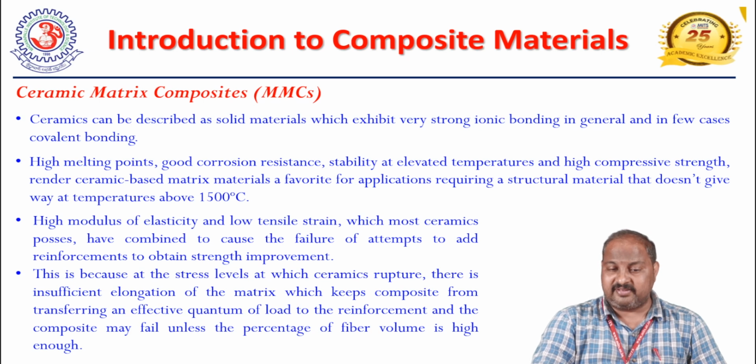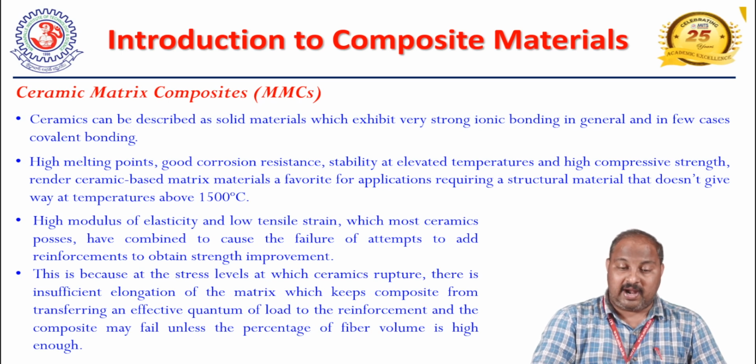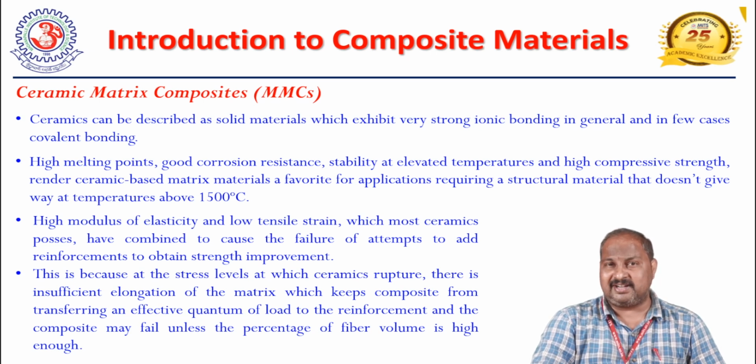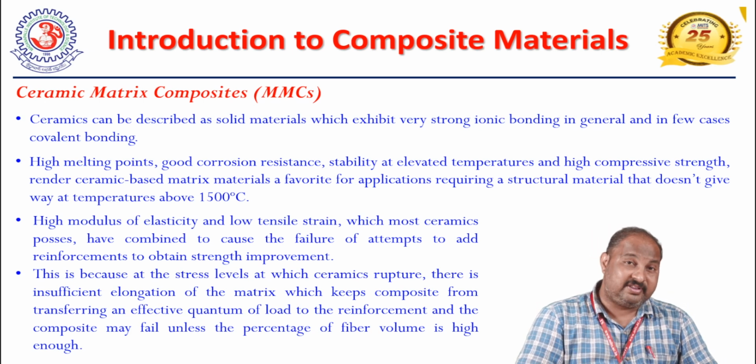High modulus of elasticity and low tensile strain, which most ceramics possess, have combined to cause the failure of attempts to add reinforcement to obtain strength improvement. One of the major limitations of CMCs is that the matrix is very brittle in nature. That's why when we add the fibers, as I mentioned in the characteristics of the composites, the strength or the